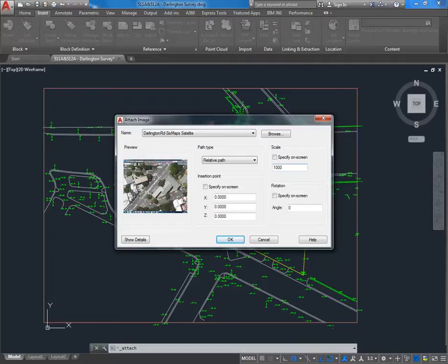If you don't change that, the object will come in with a scale of 1, which for an image will often mean it will be 1 millimetre across, which is just tiny, and it makes it difficult to work with. So if you scale it by a number like this, that will mean it'd be 1 metre across, which is much easier to work with. So that's going to make it a reasonable size as a starting point. Again, 1 metre in this case.